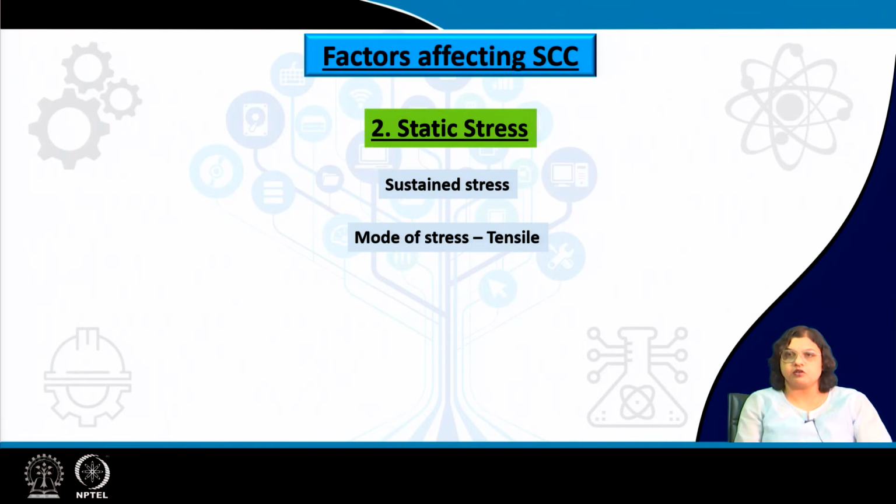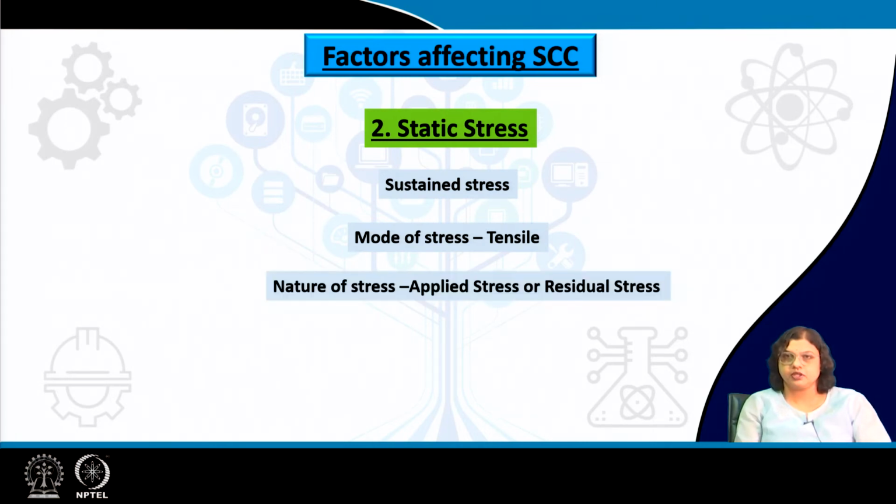So, tensile stress particularly makes the material susceptible to undergo stress corrosion cracking. How we apply the stress is not important. We can apply the stress, or the stress could already be present in the system as a residual stress. Both ways act in the same manner: this will let the corrosion reaction occur, and whatever cracks or defects are there will initiate growing, or grow at a faster rate, because of the presence of this applied or residual stress.